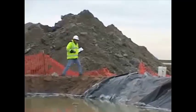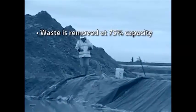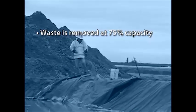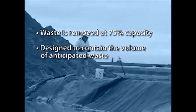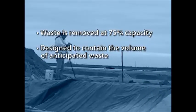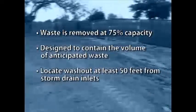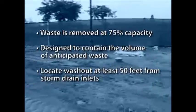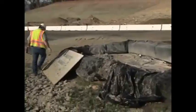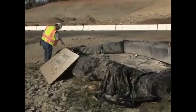During the inspection, the contractor's inspector needs to check for the following. Ensure that waste from the concrete washout is removed when at 75% capacity. Ensure that the washout is designed to contain the volume of anticipated wastes. And ensure that the washout facility is located a minimum of 50 feet from storm drain inlets, drainage facilities, and water courses. Ensure that a sign in conformance with Standard Plan T59 is installed and is located adjacent to the washout facility.